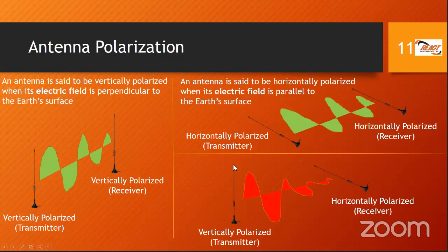And we also said that when we are using antennas and radios for effective and efficient communications, we need to have the antennas similarly polarized. So if we have a vertically polarized radio and we are trying to reach a repeater that has a vertically polarized antenna, we'll have maximum transfer like this. But notice if we have a vertically polarized repeater antenna and a horizontally polarized receiver, you notice the signal is much lower if you have a different polarization. So the important point is to make sure that you're aware of the polarization of your antenna and signal to ensure that we have maximum transfer.